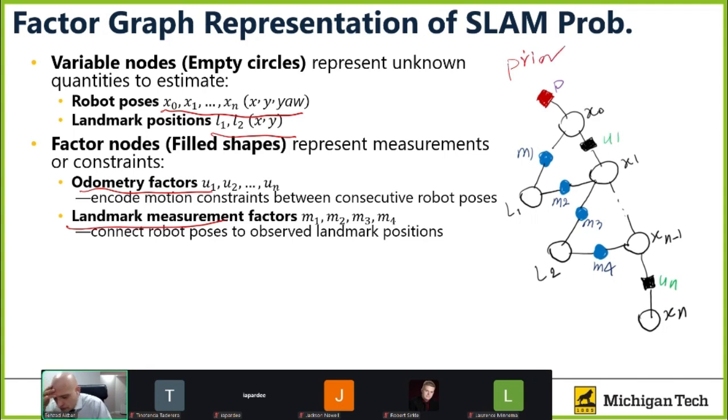Prior. So the prior is another thing that we need to have a factor for. Prior factor is a little information about the factor. Even without starting the optimization, we know those things. Like we know, for example, the shape of the table. We know the robot starts from this point, the position of the robot at the beginning. Okay, so we know this information.